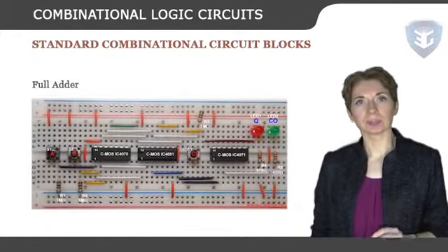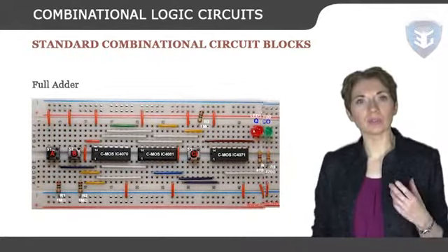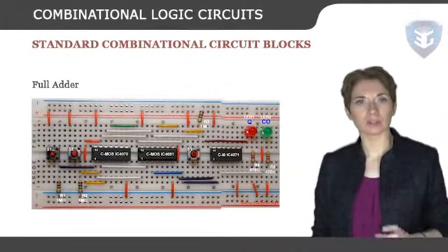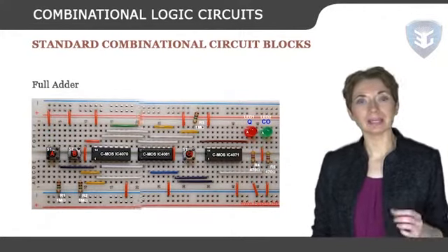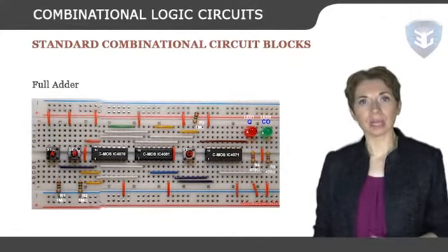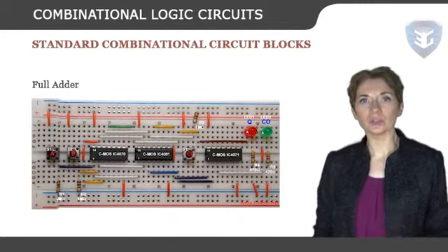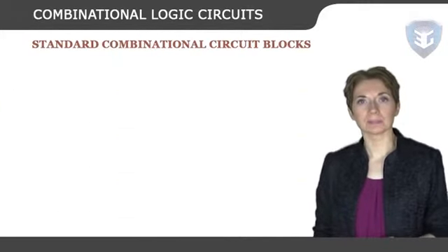Full adder. A full adder is developed to overcome the drawback of a half-adder circuit. It can add 2 1-bit numbers, A and B, and carry C. The full adder is a 3-input and 2-output combinational circuit.